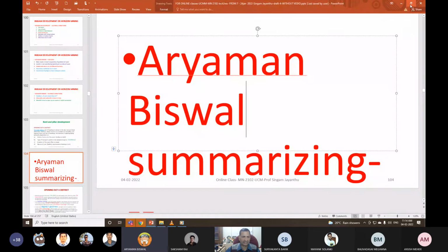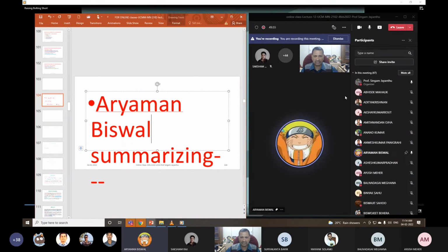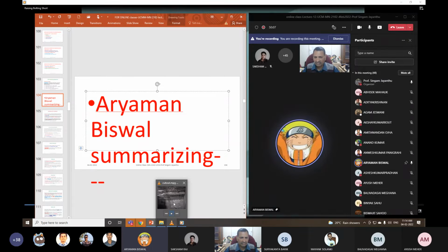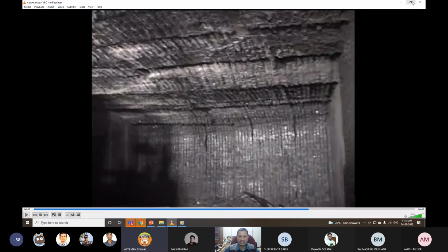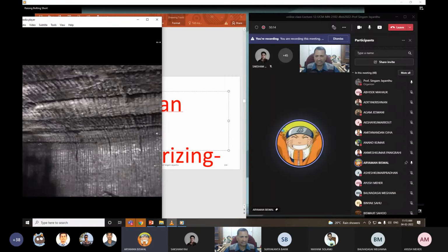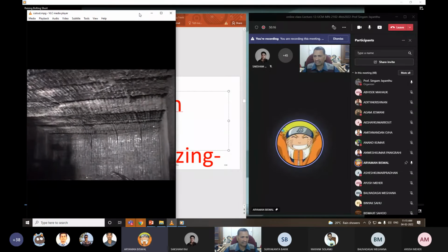Then in another video, you showed us the depillaring of a mine. Rather than blasting, we use cutting methods. Immediately after cutting, for stabilization and safety purposes, roof bolting was done using a mechanized roof bolting machine to provide support wherever it was necessary.